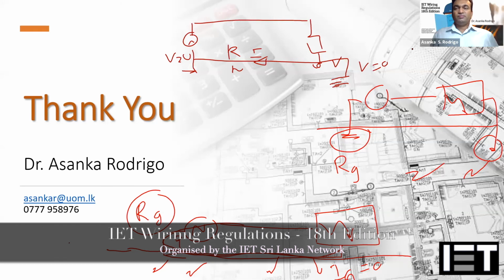Okay, understood. Next question is, what is the best practice for load diversification? I'm not sure what he is asking. Normally, if you have single-phase loads, you have to distribute them in such a way that it finally creates a balanced three-phase system. In most cases, you have to segregate the most sensitive equipment separately from the disturbing signal sources. But I'm not sure what this is asking about.